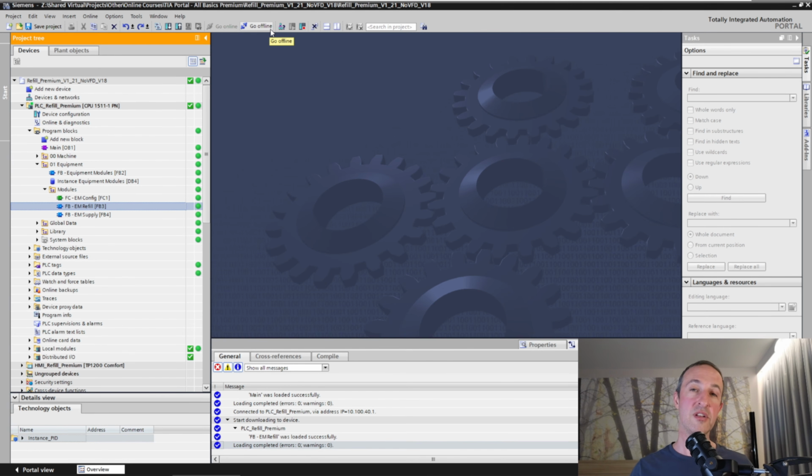This is very useful when, for example, you go on a commissioning, your company gives you a piece of software, and then you go online and you notice that you didn't get the latest software from your company. It is inconsistent. You will see some blocks are not the same as the online blocks. An upload is a very useful tool to get the consistency back, so you can continue your commissioning.